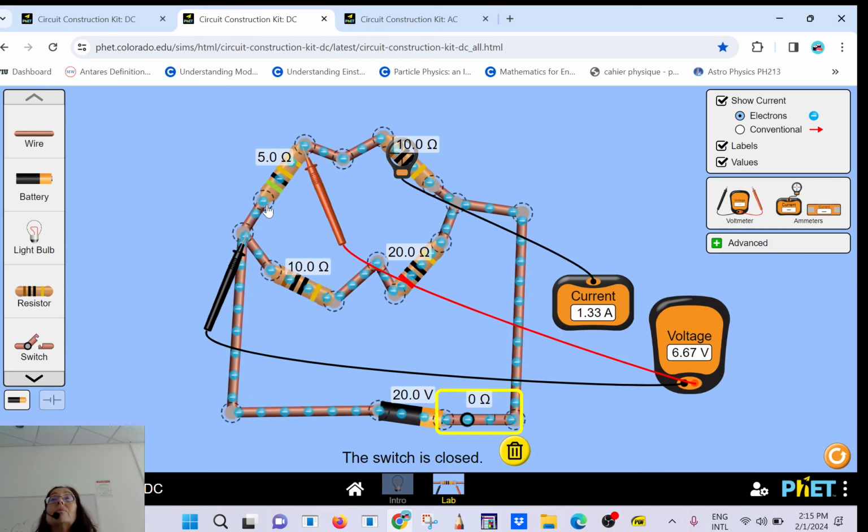You have a peak value of 34 volt. So what's going to be the RMS? 23.8. Do you all agree? You take 70%, so 23.8. I'm going to say 24 volt AC.